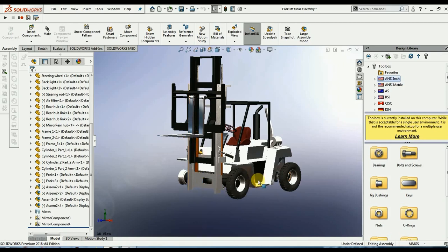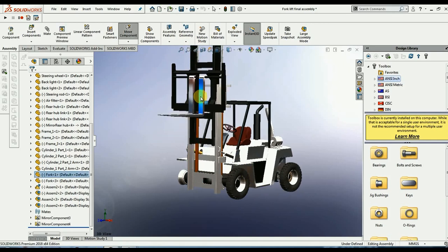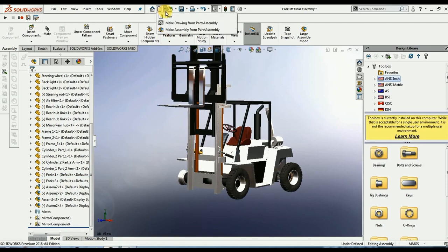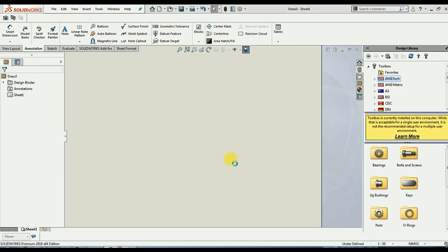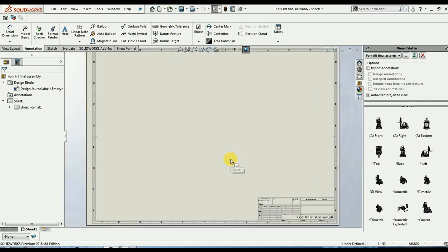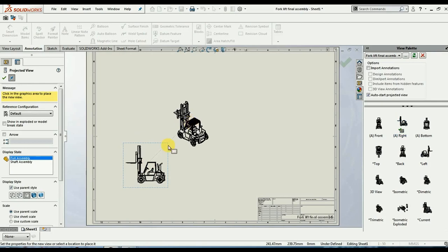And let me show you the drawings for the 3D CAD models. Now, we find the 2D part drawings, and let me show you how the assembly can be easily communicated by producing the 2D drawings. Again, the view palette automatically shows the users the different kinds of views, and my only job is to simply drag and drop into the location where I need.